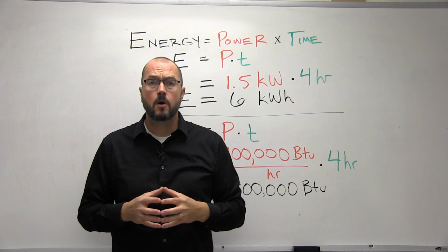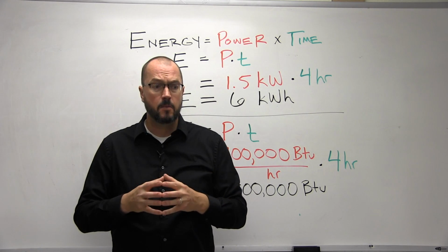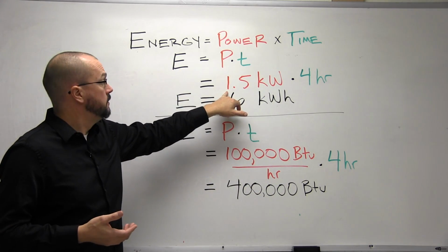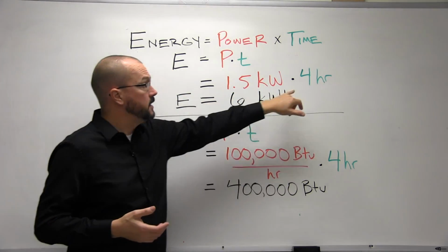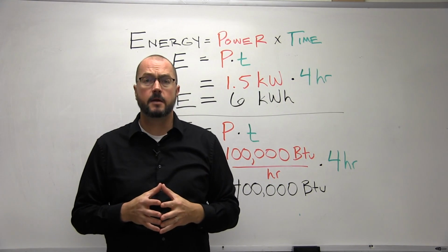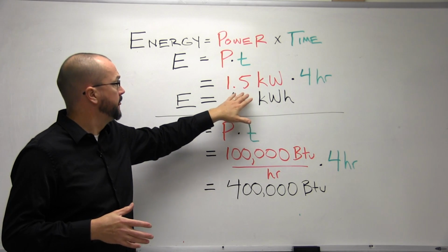If a customer wants to know how much energy something uses or how much their bill is for a certain device, this is all you have to do. Figure out how much power it draws, estimate how long it's running. Now some things like motors get a little bit more complicated, but most things are just this simple.